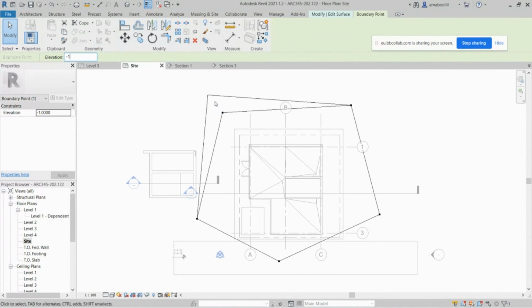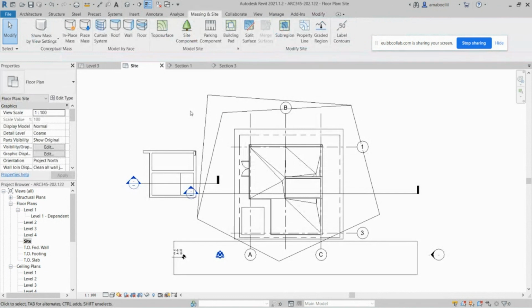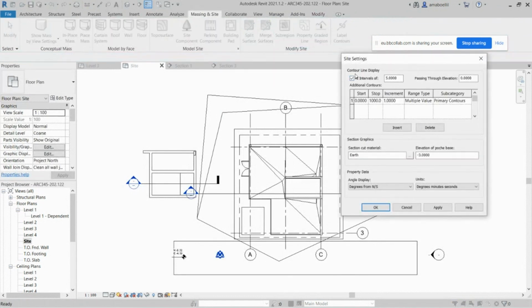But sometimes I want to increase the resolution. I want to have those appearing as several levels in here. So what I can do is, if I hit yes, I can go to this little arrow in here, and it gives me some of the intervals. This is the interval of the contour. This is at intervals of 5, so that's why the intermediate lines are not shown.